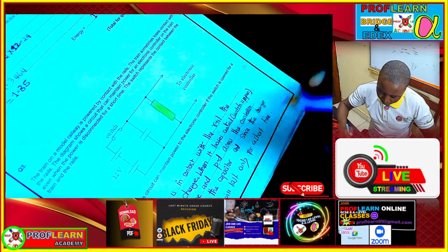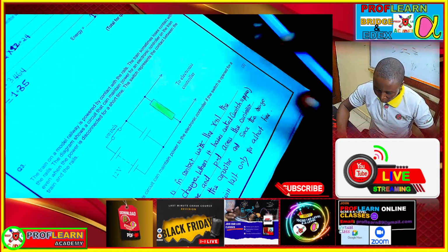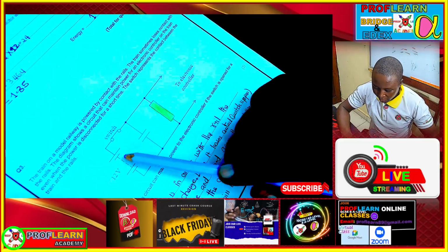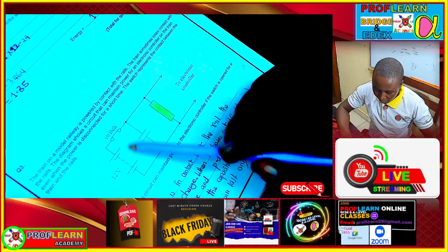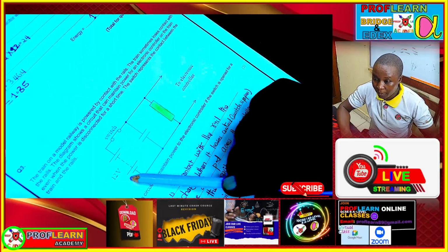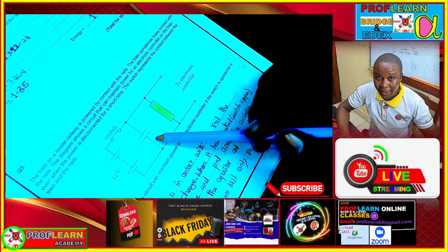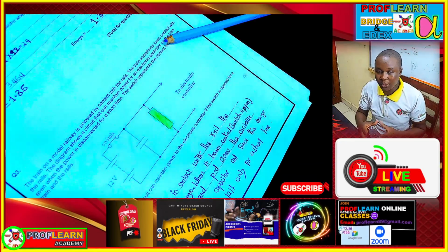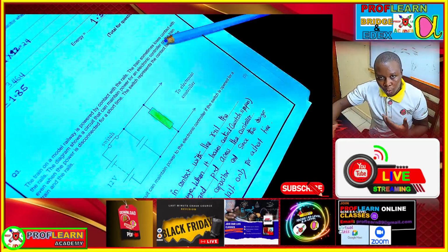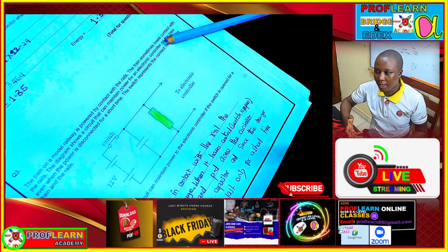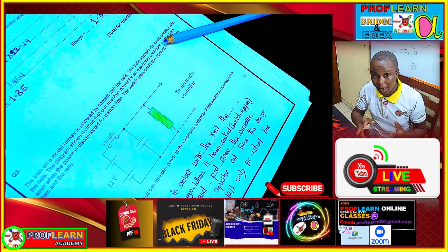And the point here is, when it loses contact, this switch is going to be open, and when it's open, the power supply cannot come from the battery, but it's going to be supplied by the capacitor, because a capacitor stores charge, and it can release that charge within a very short period of time, hence giving a lot of power.